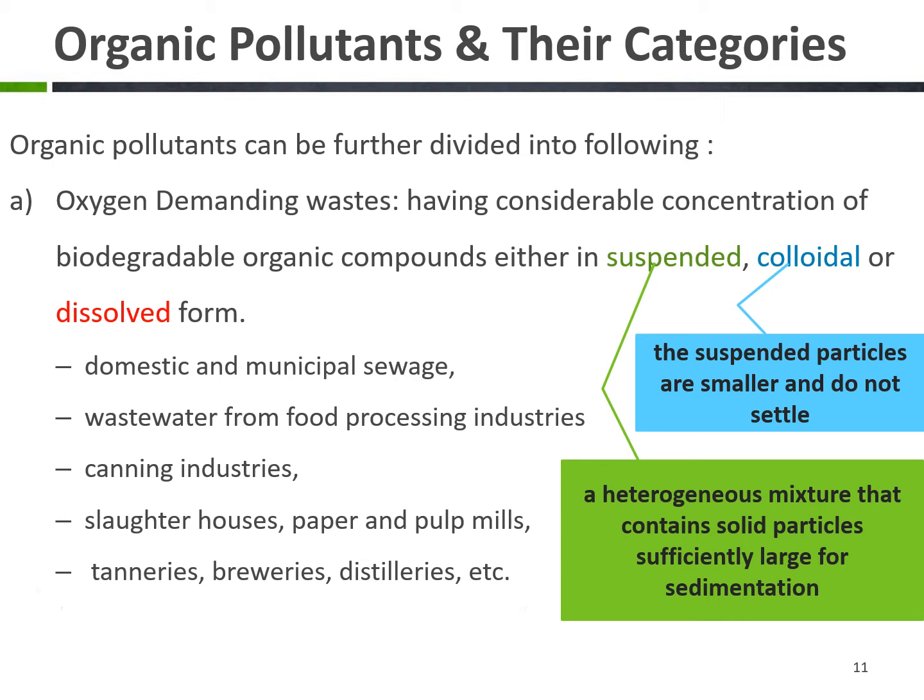Initially suspended particles are already existing and they can have a variety of densities. And then we have a category of particles which is again in suspension, but they are much smaller, and they need to be collided, mixed and merged with other particles so that their density and volume increase sufficiently to make them settle down by the force of gravity. So we are supposed to provide them sufficient driving force, so we need to provide a path. It will be talked about in the coming lectures, so that we can understand the procedure of sedimentation and colloidal particles